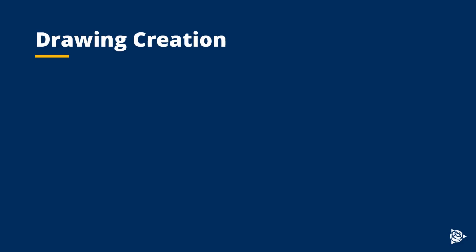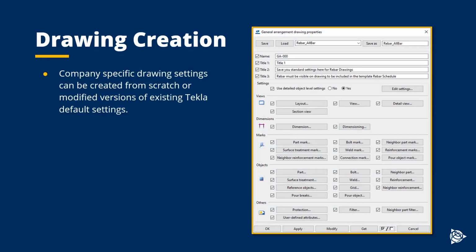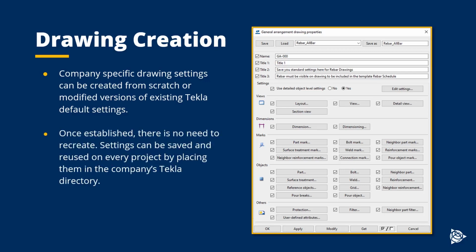detailing. And that is that typically speaking, you or other detailers are going to have your drawing settings established, right? It doesn't take too much to get them going, changing out your title block, making sure that your dimension styles and part marks are in the format that you want. And as you saw when I changed the drawing settings from having no marks to having all marks, all that work was done for me. All I had to do was adjust those marks to make sure they look clean and align them. And there's tools in the annotations ribbon to help assist with that.